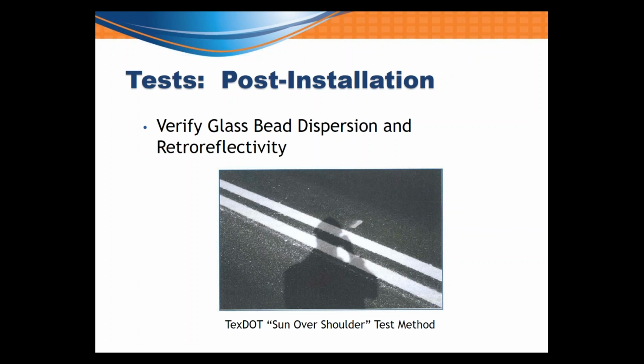Once the marking has been installed, you want to verify the glass bead dispersion and retroreflectivity. Although IDOT specifications do not require a minimum retroreflectivity, markings are required to be retroreflective. Therefore, the sun over-the-shoulder test from Texas DOT test method TEX-828-B can be used to assess retroreflective properties.